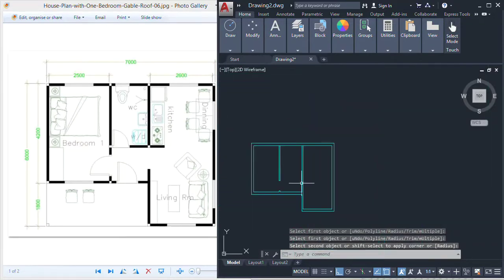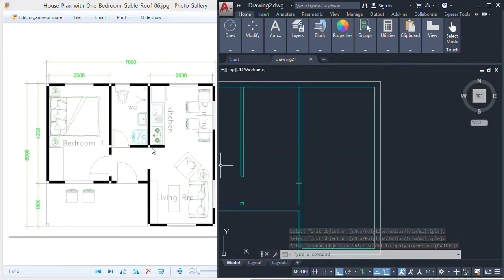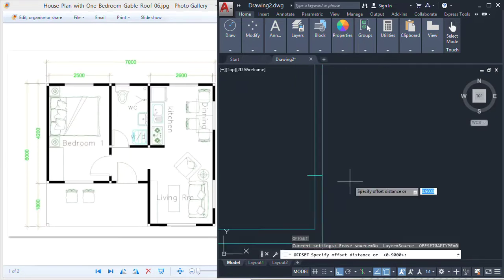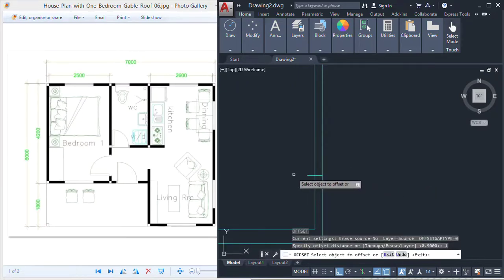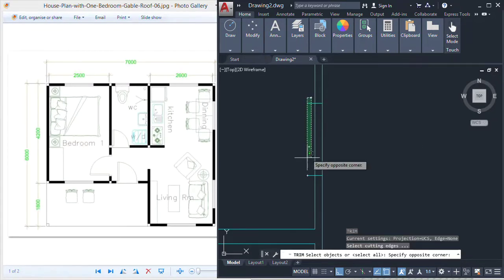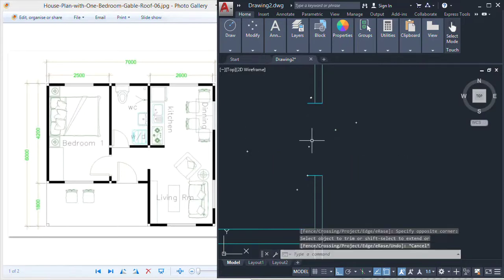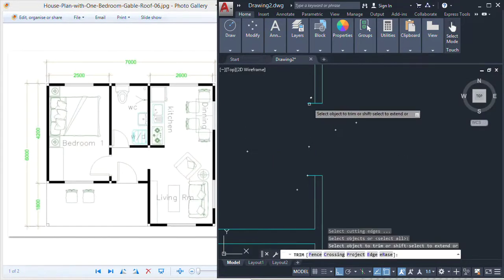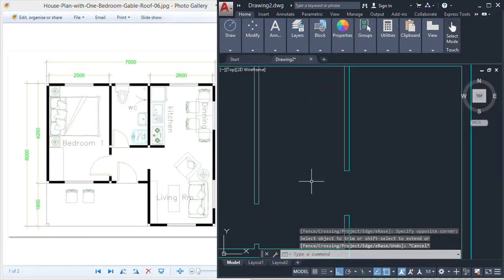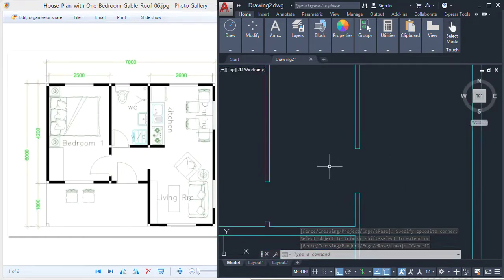So as you can see, I have another meter between these two, so I have a line here which I'm going to use the offset command for. I will offset it for 1 meter, and as you can see, again I have a boundary here. I can order TR, select my lines and delete these two, and again another TR and space and delete these two. So as you can see, I formed this opening, and from this opening I'm gonna have the bathroom wall.